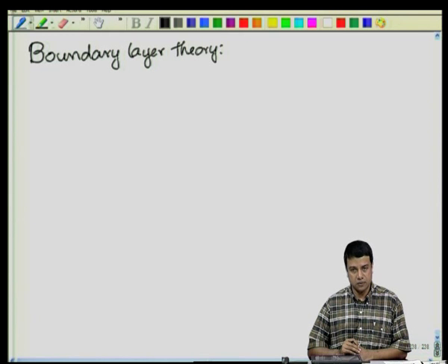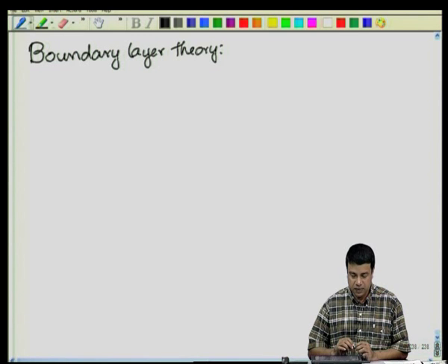First, we looked at low Reynolds number. Reynolds number, as you recall, is rho u d by mu, where d is the characteristic length. We were first looking at low Reynolds number, where the velocity or the length scale is small, so that viscous effects are dominant. And we looked at various ways of solving the Navier-Stokes equations. The methods of solution are broadly similar to those for the diffusion equation, the Laplace equation, in the case of heat and mass transfer.